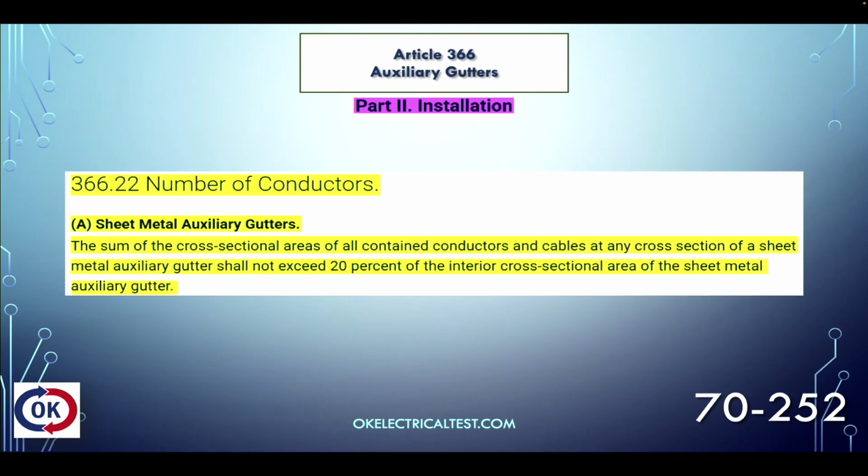Let's go to Article 366. Article 366 is auxiliary gutters, and we're going to go to 366.22, number of conductors. And letter A, we've got sheet metal auxiliary gutters. The sum of the cross-sectional areas of all contained conductors and cables at any cross-section of a sheet metal auxiliary gutter shall not exceed 20% of the interior cross-sectional area of the sheet metal auxiliary gutter. So maximum fill that we can have in a sheet metal auxiliary gutter is going to be 20%.